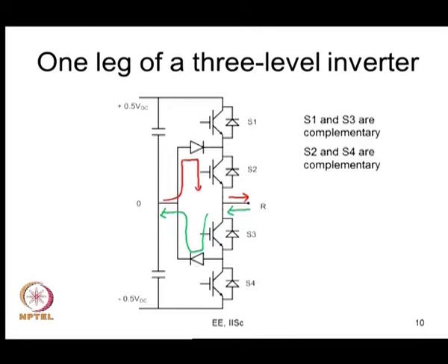So if you see it this way, we have a capability here. There is a voltage source, and this is the pole, and there are 3 different throw voltages, and this converter has an ability to apply any desired throw voltage at the pole, irrespective of the direction of current. That is an attribute of voltage source converters. Let us say the current is like this. Now you want this voltage to be applied, you turn on these two. So your current conduction will be like this through the transistors, and it will go along like this. Now if the current conduction is in the opposite direction, then it would go like this and go back there.